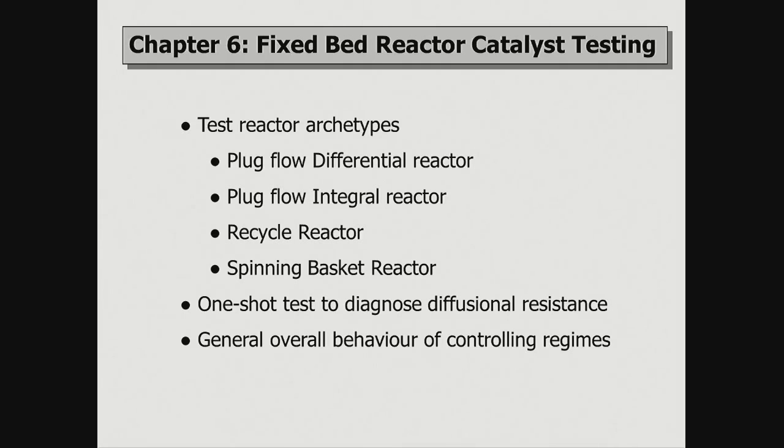Okay? So, now we meet some reactor types. We've had a very basic introduction to the sort of design equations. Now we're going to say, well, how can we pull all this together? We've learnt about the mass transport, we've had some words about diffusion, we've had some words about active site and surface reaction limited. So what does that mean to us? So let's just have a clear definition now of reactor types. Differential and integral reactors. You've heard me say it. Differential, low conversion, integral, high conversion or medium conversion.